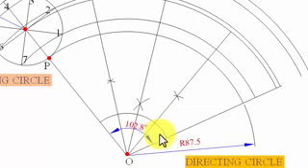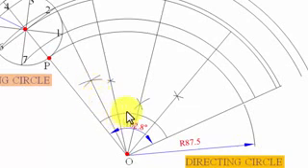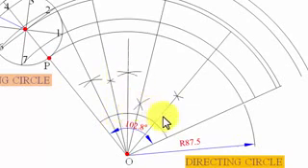Initially there was only one angle, 1 was made into 2, 2 was made into 4, and now what we're going to do is make 4 into 8. So let us say we have this angle over here. Keep one leg of your compass here and make an arc, and then with this as center, again make an arc, something like this. So this is the intersection point. The same has to be repeated in this section also. With this as center, put an arc, with this as center, cut an arc, something like this. Same here also, with this as center and with this as center.